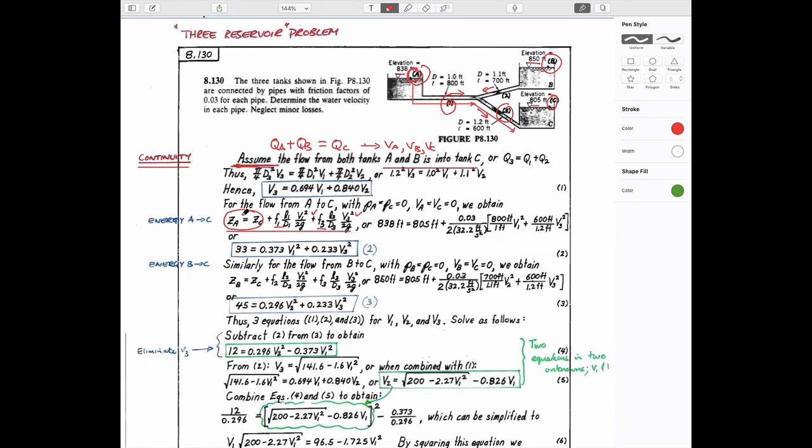And so we definitely know this, but we don't know what the velocities are. We can write a circuit that goes from this tank here, from B to C, which is the next one, which would be the elevation changes between these and the friction factors or head losses in pipe 2 and pipe 3, which are these parts here.